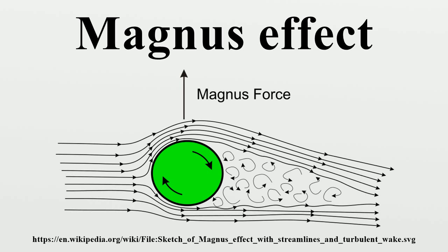Physics. A valid intuitive understanding of the phenomenon is possible, beginning with the fact that, by conservation of momentum, the deflective force on the body is no more or less than a reaction to the deflection that the body imposes on the airflow. The body pushes the air down, and vice versa. As a particular case, a lifting force is accompanied by a downward deflection of the airflow. It is an angular deflection in the fluid flow aft of the body.